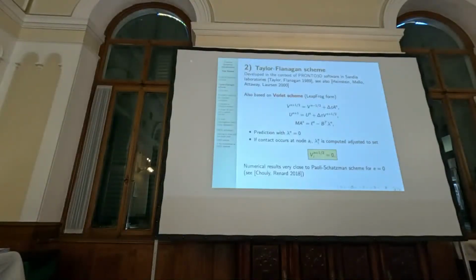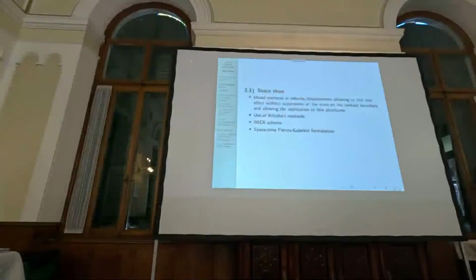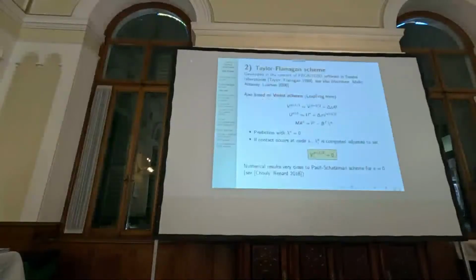And the trick is on the half time step. The velocity is prescribed to 0 if there is contact, to enforce what is called the persistency condition. And this leads to stability, but this leads also, of course, to dissipation.